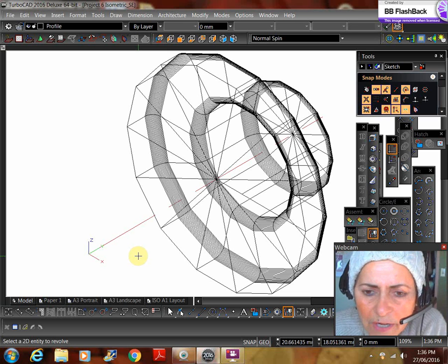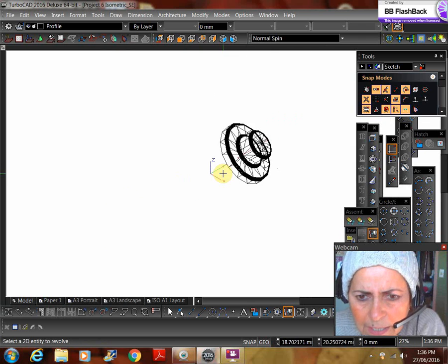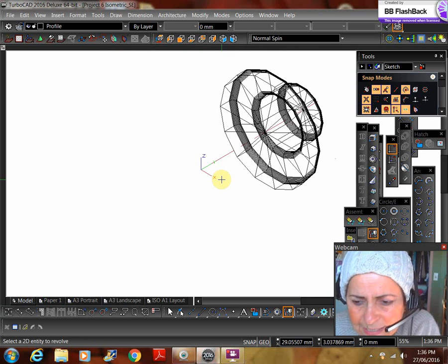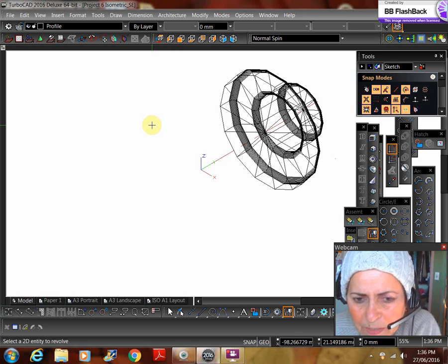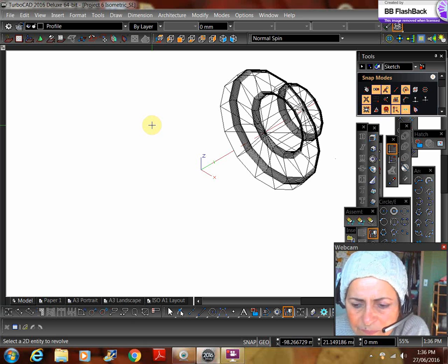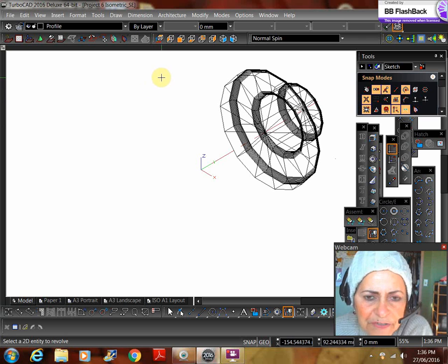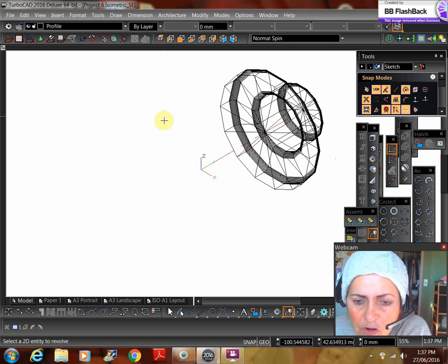There is another way that is harder and is more difficult at this stage. I don't want to say about this one. It is to rotate it about the z-axis, and that requires rotating the axis of y, and then changing the plane of this 2D object that we revolved. That is hard at this stage for the learners. So what I did, I just rotated it around the axis, and you see how the revolve works.